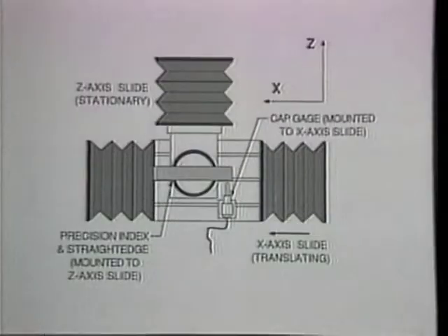As illustrated here, non-squareness of the axes of motion can undermine the positioning accuracy of the tool relative to the workpiece. Fortunately, today's high-speed computer processors can facilitate error correction techniques which can compensate for these types of machine errors. However, accurate measurement of the error values and the repeatability of those errors is necessary before any error correction schemes can be implemented. The procedure for this measurement is quite straightforward.